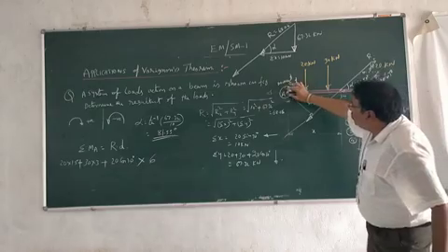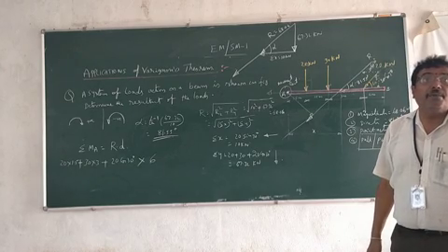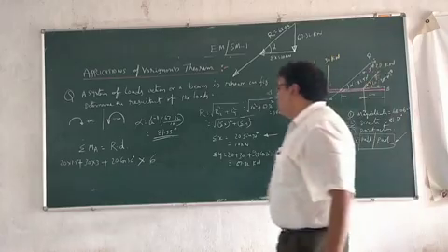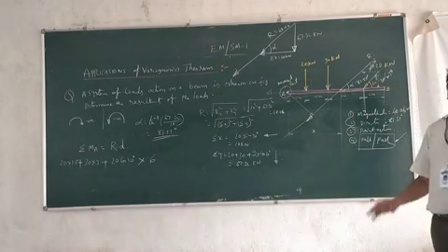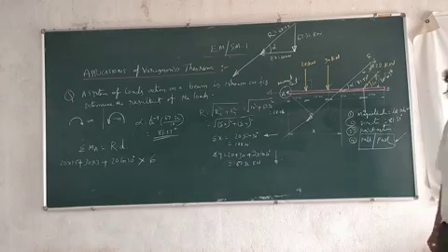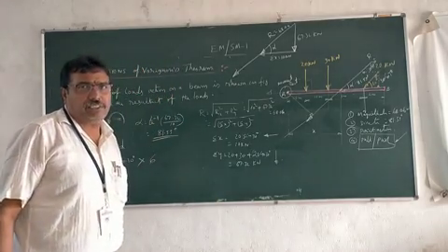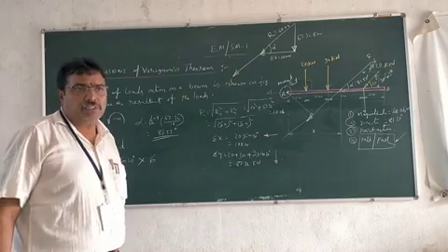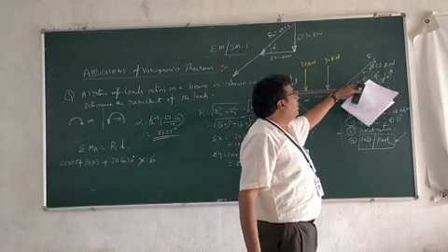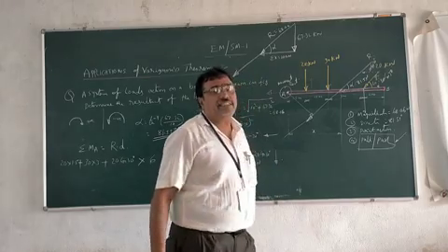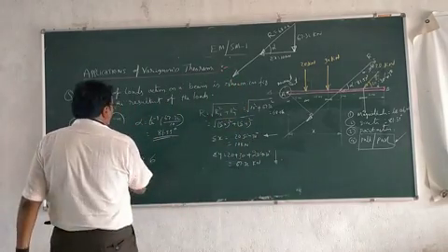And one more is acting like this. That means there is no distance between the force and the moment center. That's why there is no effect. Your x component gives no effect in moment. It is not giving any moment, any rotational effect, by the x component of this 20 force acting at 60 degrees to the beam. Okay, that's all. Right side.